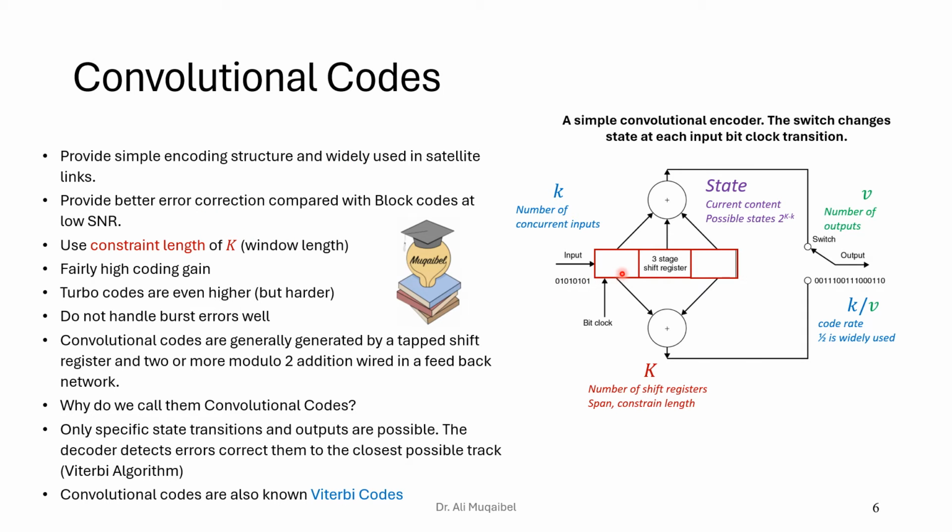It's a continuous process. For example, you see here in the circuit, the input will come as a stream, and as the stream gets in, here we are showing one arrow, so there is only one bit. Another stream will get at the output. So we have two here. We take one from up, one from down, and so on. So here is a rate 1/2 code, and it's a continuous process. We don't take blocks here.